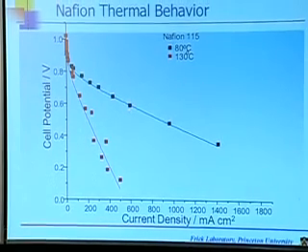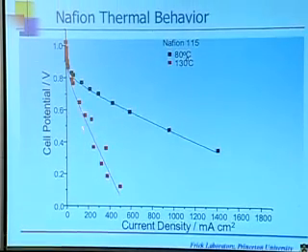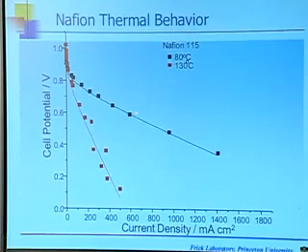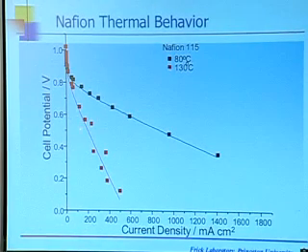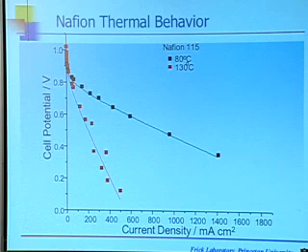We've taken our R from that value to this value. And so where we were getting 3/4 of an amp out before, at 0.6 volts here, we're getting a couple hundred milliamps out. That's a dead cell. What this data doesn't show you is if I now go and cool the cell back down and run the curve again, it looks just like the red curve. It does not recover.